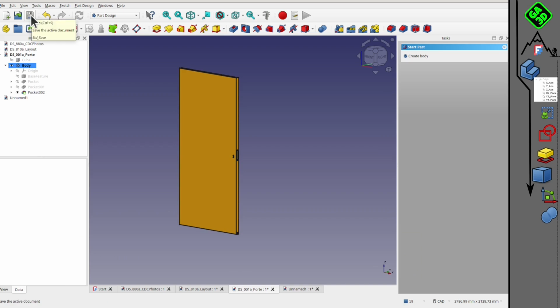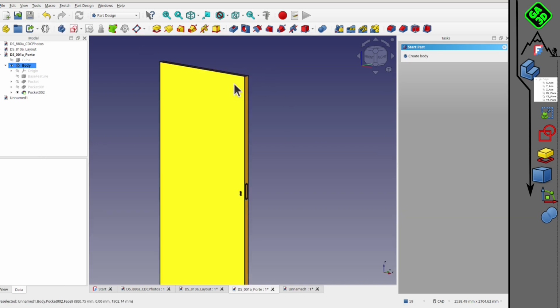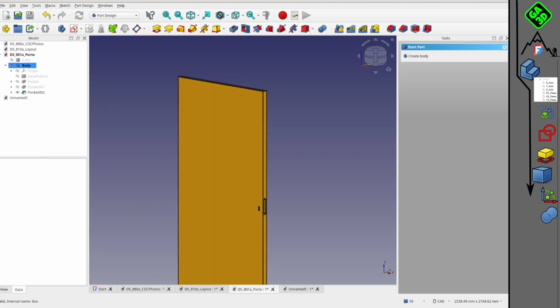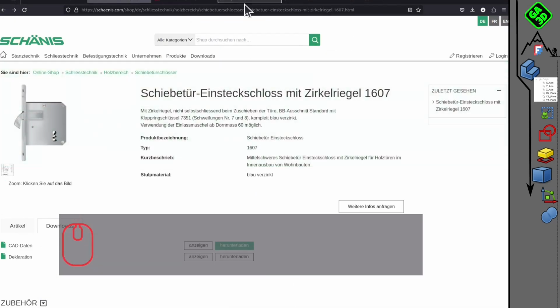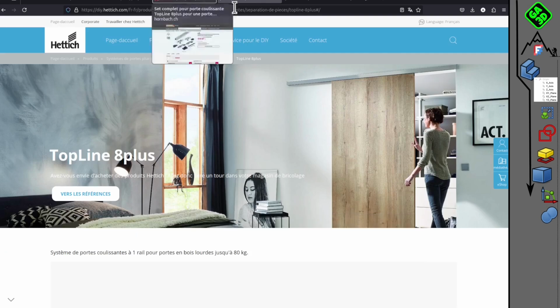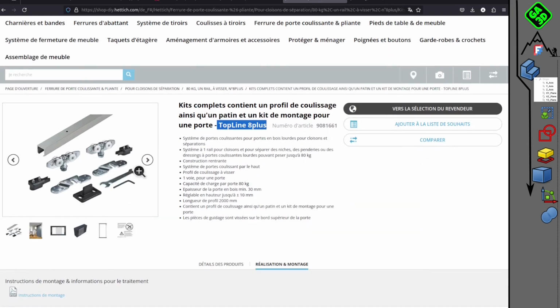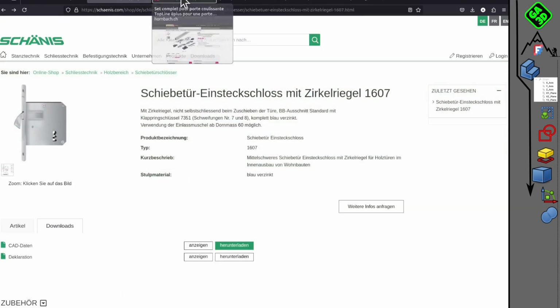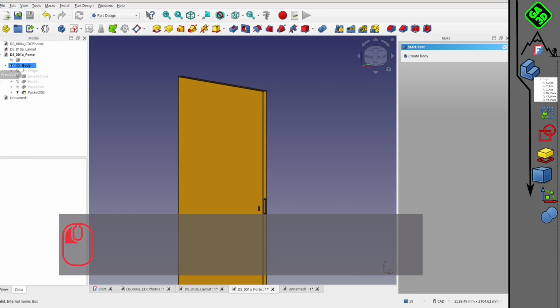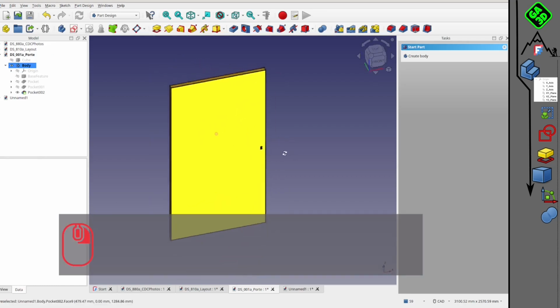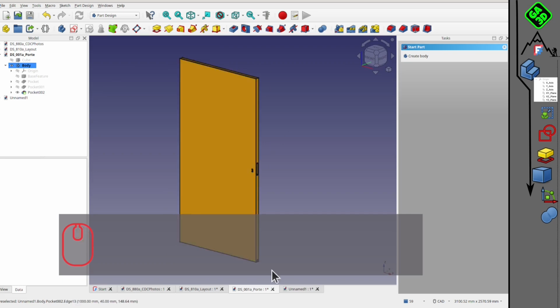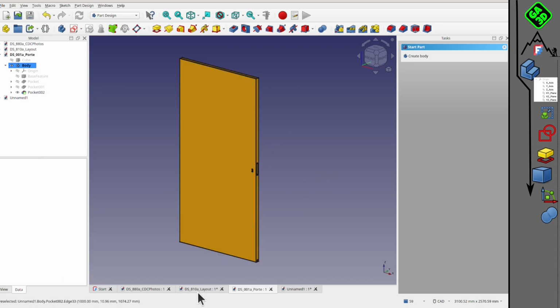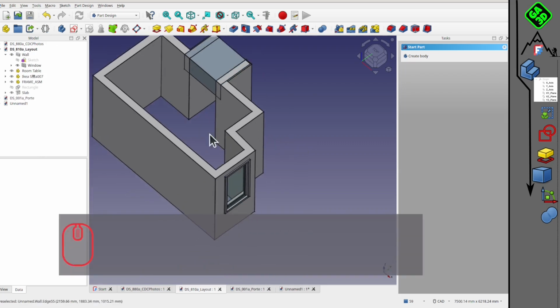So here, typically, we need to add the door, 2 posts, and then a beam to support the rail system. So the door, we'll draw it quickly. We give it a name. Here we go. We change workshops because there's no need to be online for this.